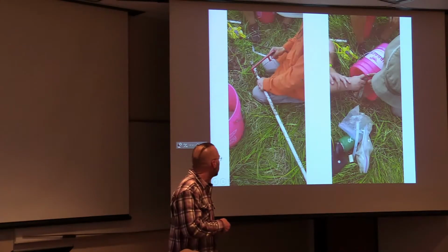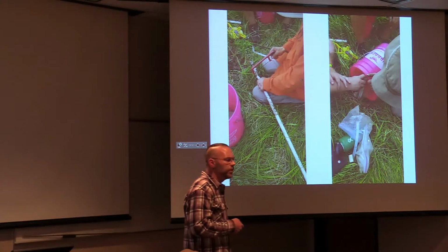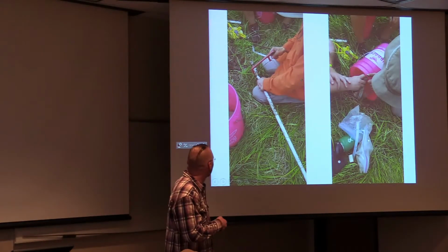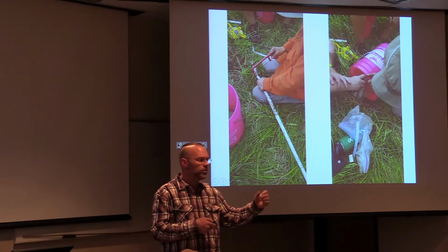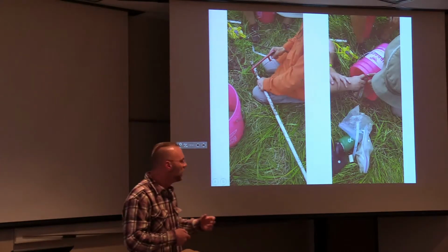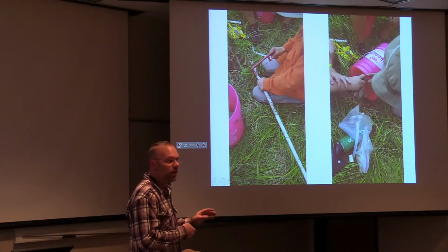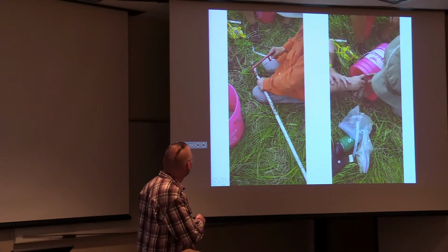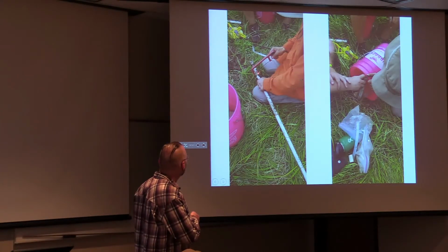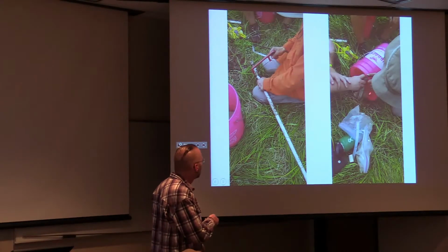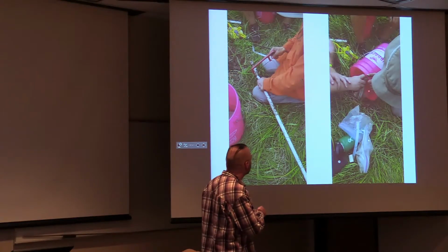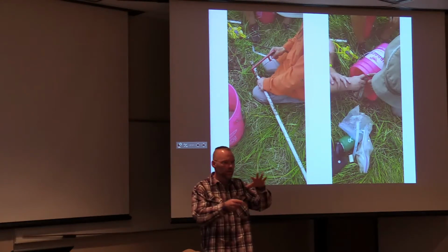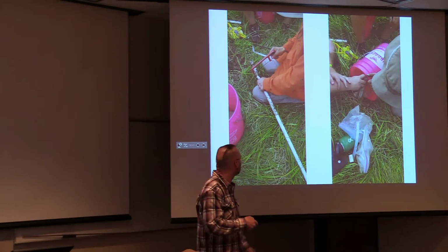Here's a picture of us. I took my hydrogeology field camp to this site, and we did several tasks. One of them, we added a few deeper wells, maybe 6 to 8 feet deep, a couple of those near some shallow wells for understanding the upward and downward movement of groundwater. And that is Evan right there, hacksawing and making slots. As he put it in the borehole, he's surrounding the screen with sand there, and then later a little bentonite to keep surface water from coming into the well.